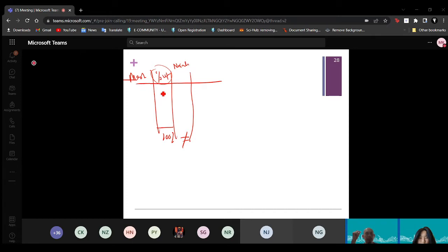Let's say you add on everything. Let's say this is 4.4, 16.8, and so on. You add them up, and you get 98% here. So you have a balance of another 2% to become 100%, right? So what you need to do is normalize the weight percent. How to normalize?